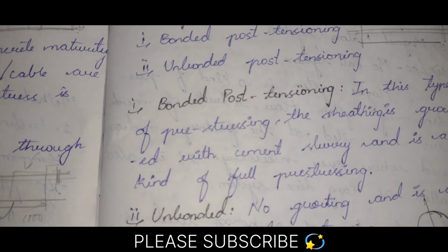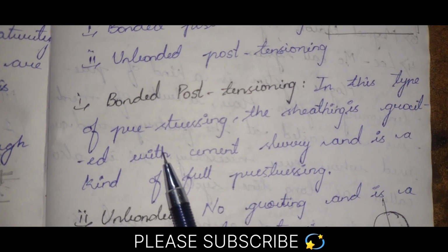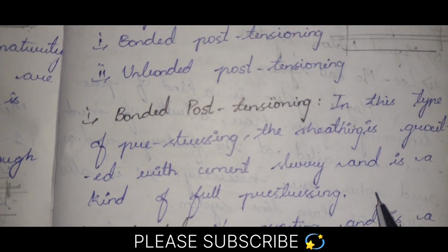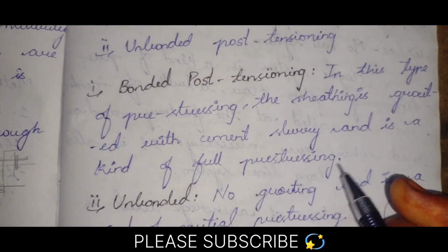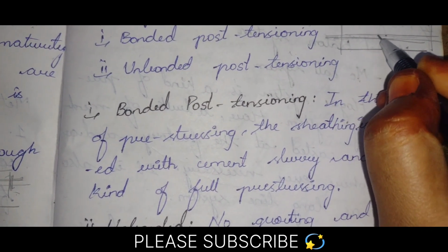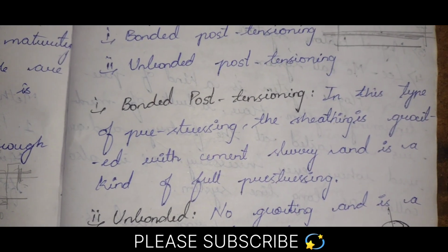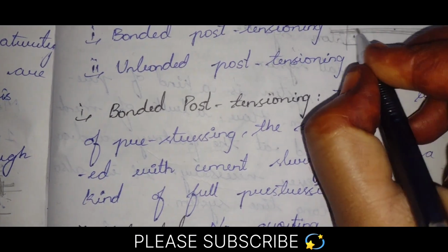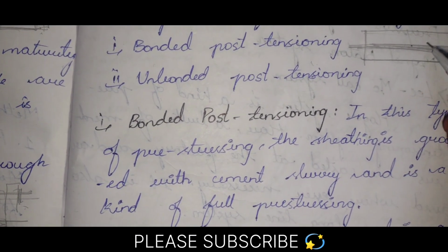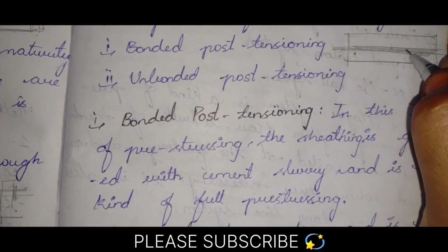Two types are there. First comes bonded post-tensioning. In this type of pre-stressing, the sheathing is grouted with cement slurry, and it is a kind of full pre-stressing. You have understood, right? Once the wire is placed in this, there will be some gap, so we fill this gap with grout. Whenever we fill the entire gap with grout, we call it bonded, because there is a bond between the concrete and the wire. So this is bonded pre-stressing.